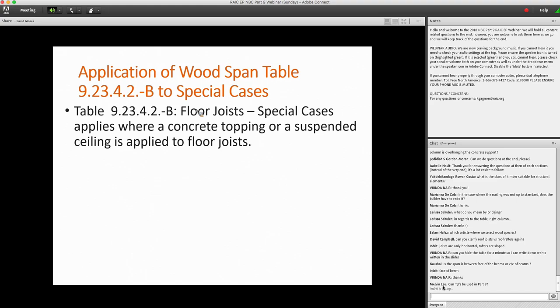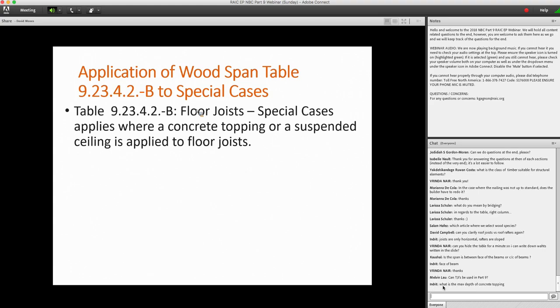And actually, as a product, the I-joists are quite nice because they will rate the capacity by including the effects of the sheathing, either plywood or OSB, and whether or not concrete topping has been added, and what the nailing or screwing pattern is, or whether the sheathing is glued or not glued. So there are a lot of other variables in designing I-joists.